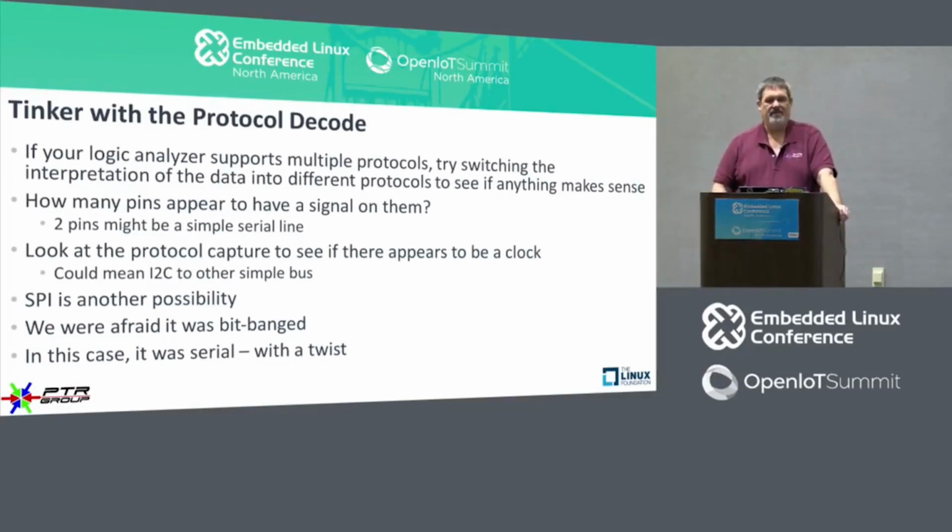How many pins are involved with the signal? Is it something that I can see in just 2 pins, in which case it's probably RS-232, but does one of the pins look like a clock? When you hook it up to the Saleae units, you're going to see this thing going ting, ting, ting, ting, ting, ting, and that's probably I2C. So when you start doing interpretation for I2C, you'll be able to decode the master and slave interfaces.